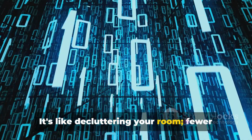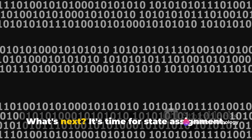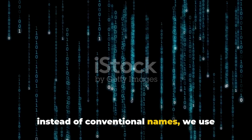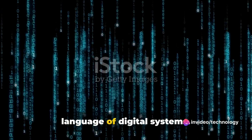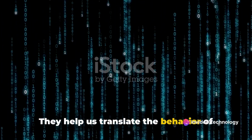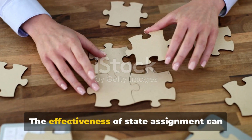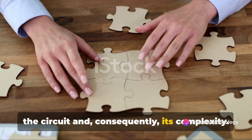It's like decluttering your room. Fewer items mean less mess and more space. Now let's imagine you've successfully minimized your states. What's next? It's time for state assignment. This process involves assigning binary codes to the states in your sequential circuit. Consider it as naming your states, but instead of conventional names, we use binary codes. Why, you ask? Well, binary codes are the language of digital systems. They help us translate the behavior of our circuit into a form that can be understood and processed by the system. The effectiveness of state assignment can have a significant impact on the logic of the circuit and consequently its complexity.